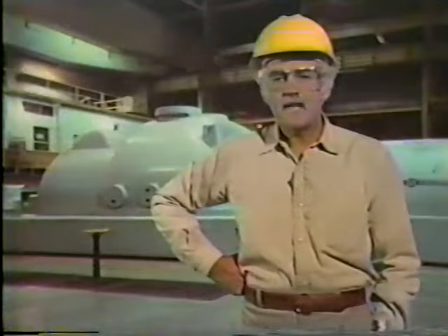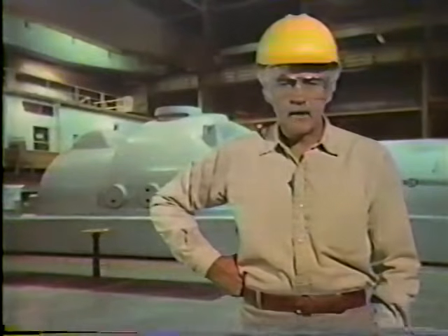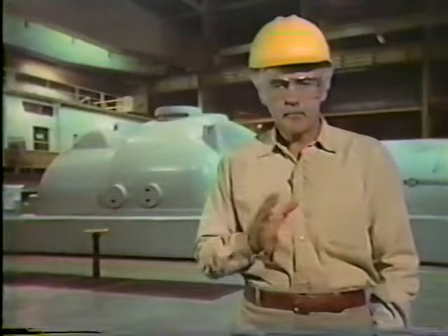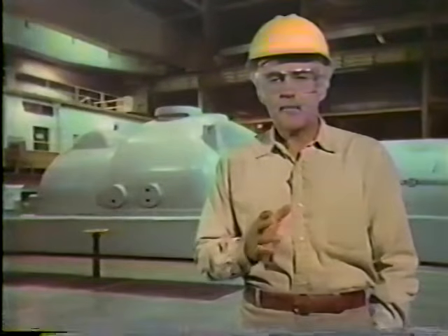turbine. Now that we've seen how main stop valves and control valves work separately, we need to learn how they work together. This is important because during startup, the operation of one set of valves is related to the operation of the other. In this illustration, we've combined a main stop valve and a set of control valves. Although there are usually 2 to 4 main stop valves, we've only shown one here for simplicity.